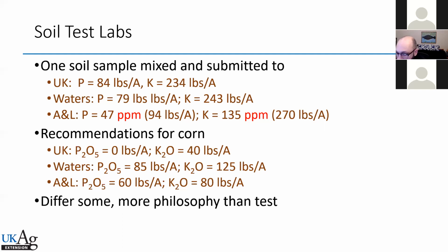We don't recommend applying on frozen ground because you get a lot of runoff, which has environmental impacts. It's slow waiting for things to dry out, but my biggest concern of running across ground right now is how wet it is, and how that soil is going to hold up to that traffic. Because with a little bit of compaction, you'll be paying for that compaction for 20 to 30 years. It just doesn't go away.